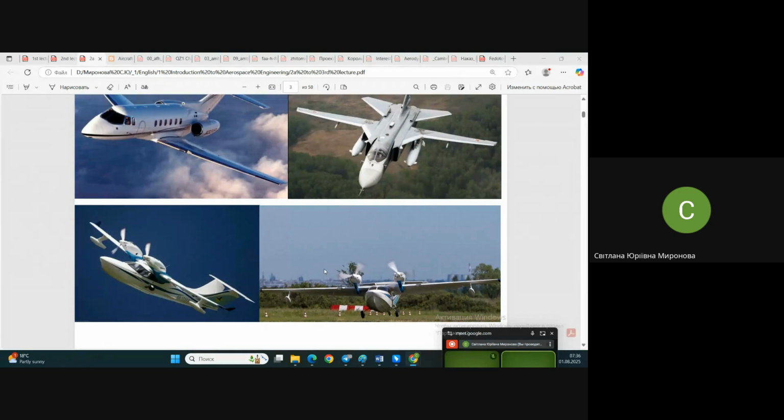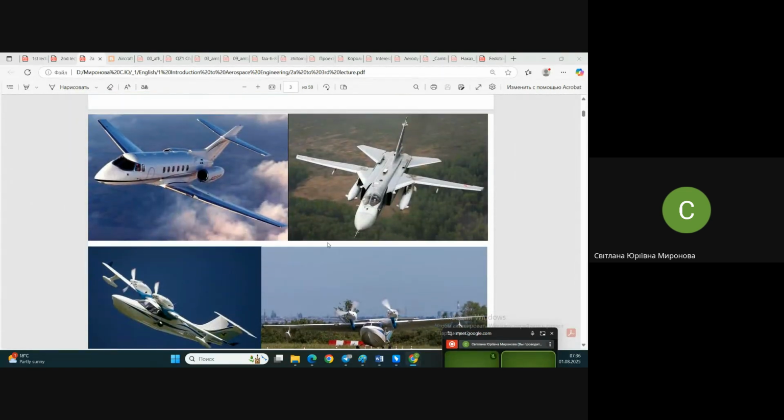And what about the speed? How may we decide something about the speed of these airplanes? Shapes, no, rather sharp, let's say. This one, that one, no, rather similar noses. How to decide what it is? Also, so-called relative thickness of profile may help us. Where we have a more sharp profile, more thin and more sharp at the leading edge, it's a supersonic airplane. Where we have more thick and rounded, so-called like airfoil at the leading edge, it's subsonic.